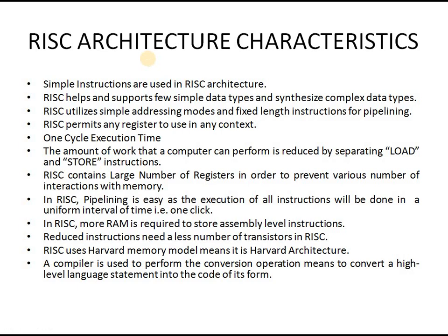RISC architecture characteristics. Simple instructions are used in RISC architecture. RISC supports few simple data types and synthesizes complex data types. RISC utilizes simple addressing modes and fixed length instructions for pipelining.